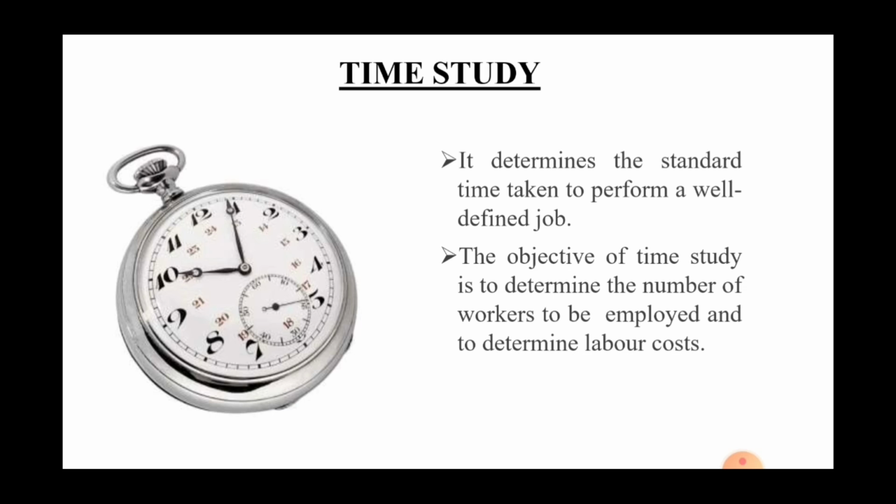In the procedure of time studies, we can use different types of methods like the stopwatch method. It is the most commonly used method in time study, according to which we can calculate the actual time and compare the standard time with the actual time to identify the performance of workers.